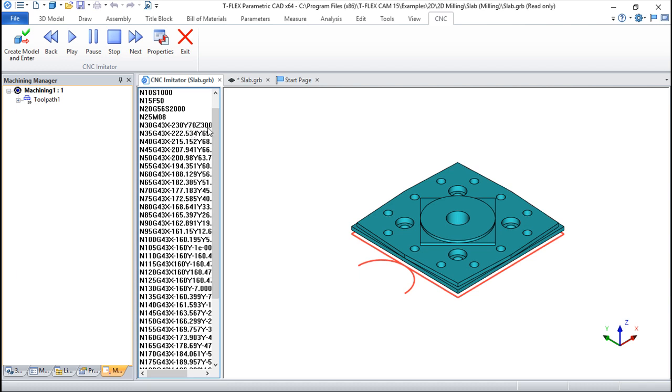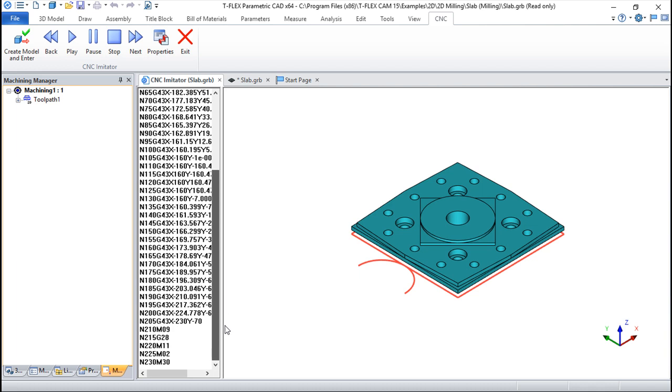Okay, the Z, the plan height, we have it here, and it goes down, down, down, down, and you see in the end we have also our parameters, and in the middle we have this G43, which is not okay in the definition. You see that it's present in this cycle. This is to show that for the specific function it can create the toolpath with these parameters.